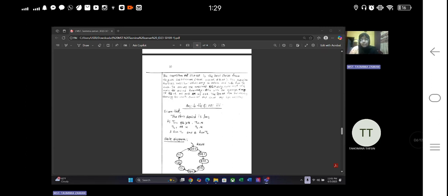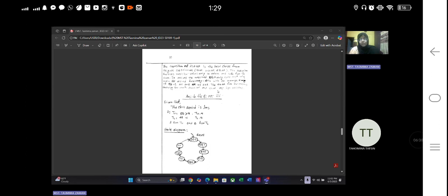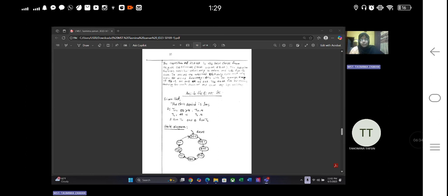This capacitor gives resistor values that are easy to obtain and safe for the timer. It achieves the required 56% duty cycle and the desired frequency of 10 Hz, with timing of 56 ms on and 44 ms off. The 470 microfarad needs low resistors drawing too much current, and 50 microfarad needs very high resistors.